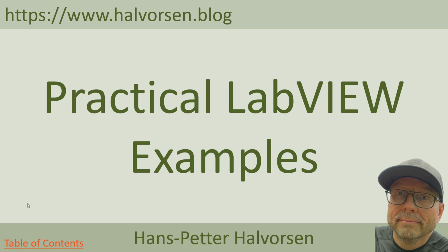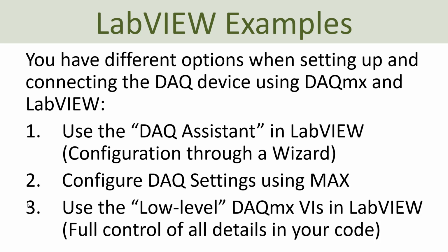So now we are ready to start creating some basic examples in LabVIEW, and I will create 3 different ways to communicate with the DAQ device. First I will use this DAQ assistant, then I will configure the DAQ settings in the MAX, and then finally I will use the low-level functions. So then it's up to you which alternative you want to use in your LabVIEW application.